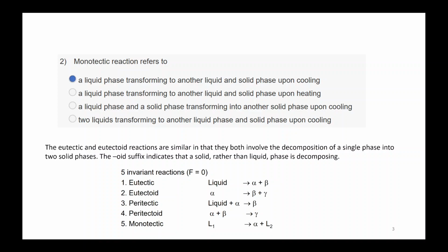When we say strain hardening, it is the accumulation of dislocations and their interaction. So it starts after the yield point. Up to the yield point, it is only elastic deformation. After that, strain hardening starts, and it occurs up to your fracture point.